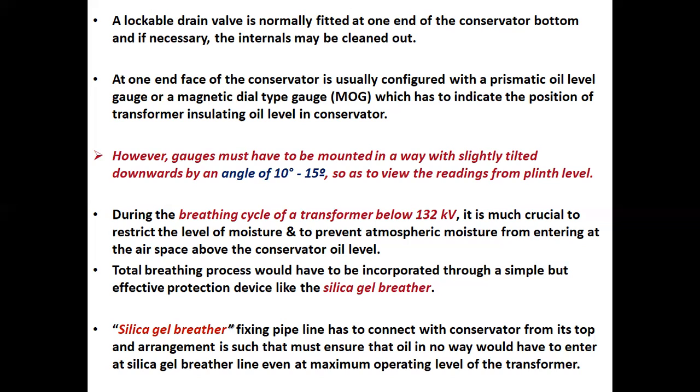The total breathing process is incorporated through a simple but effective protection device like the silica gel breather. The silica gel breather pipeline connects with the conservator from its top, and the arrangement must ensure that oil in no way enters the silica gel breather line even at the maximum operating level of the transformer.